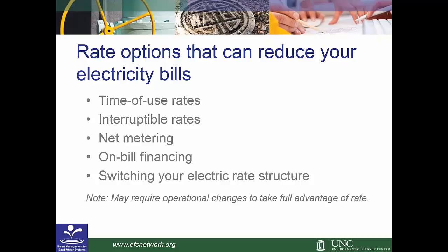Now, I think you frequently will not see that for a lot of you who are small water systems around the country, but some of you might have a time of use rate, and if you do, you can look at things like, can you switch some of your pumping from a higher electric cost time of day to a lower electric cost time of day or time of the week? And you may or may not have discretion over that, but it's something you could look into.